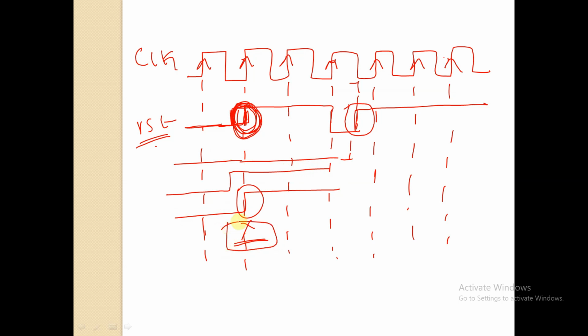Okay. That's why in our sessions, in our class also, I've discussed while writing a TB: for a posedge design, we will drive the reset signal or any other input signal. If the design is working at posedge of clock, then we will drive the signals at negedge of the clock only, to avoid setup time and hold time errors.